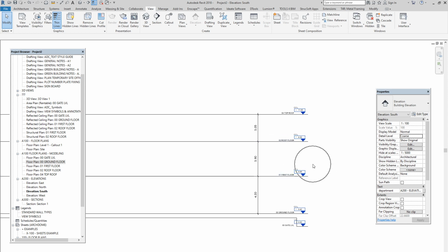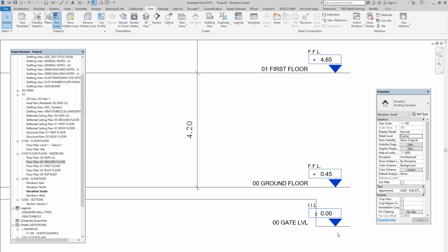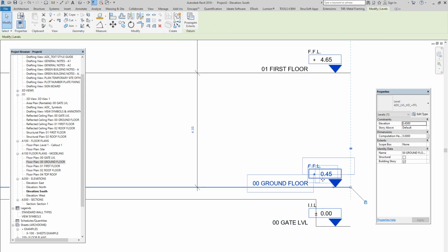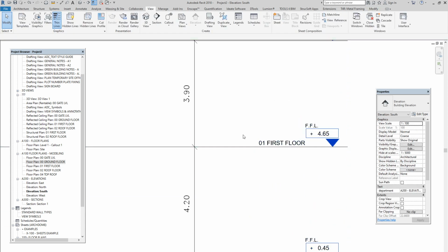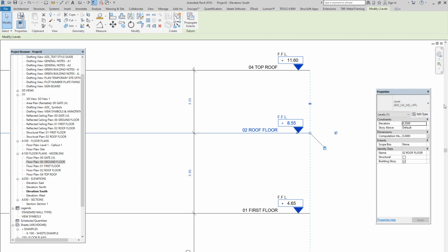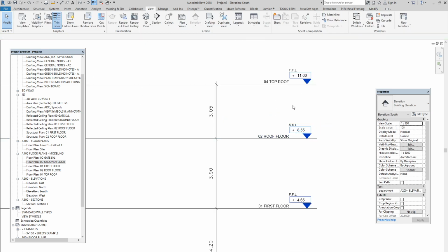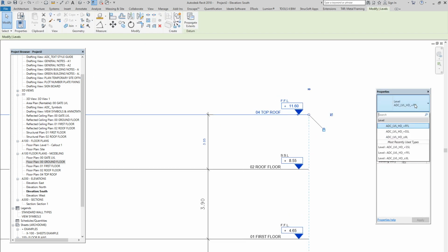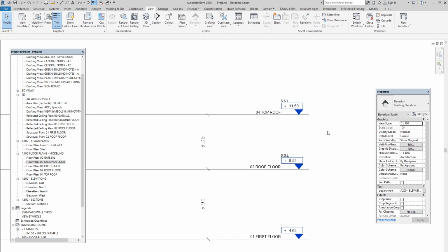Okay, one more thing related to the levels: creating the type or the classification as we agreed. This is FFL. If we select that one, FFL as it is, this is also by default coming FFL. Now the roof is supposed to be SSL, not finish. Just select that one, from here just drag down or click down, tell it I want SSL. That's all. Already the ID has been changed, the same here. Okay, SSL. Okay, Control Z, just to come back, make it FFL.